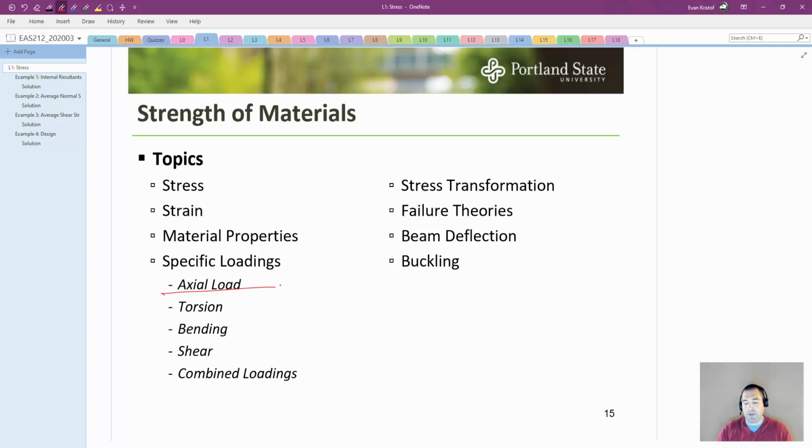And then once we've covered deflection, we can then transition to column buckling. Buckling is an effect in a compressive member where if you have a column, a purely compressive member, and you're just loading it axially, with force parallel to the long axis of the member, there is an amount of force P that will cause that column to become unstable, where any little horizontal force would cause it to buckle out suddenly in a very unexpected failure mode.